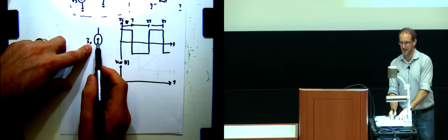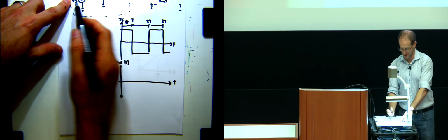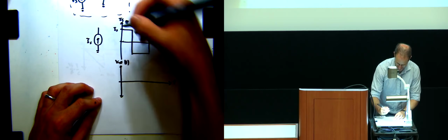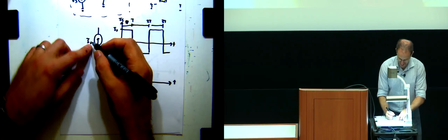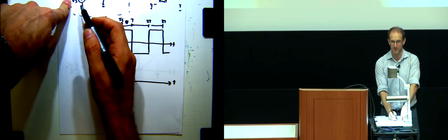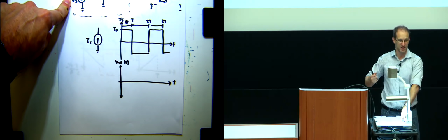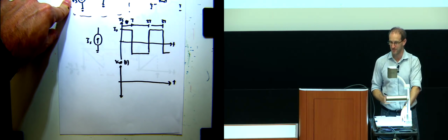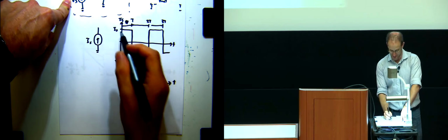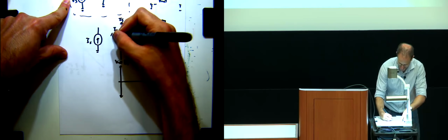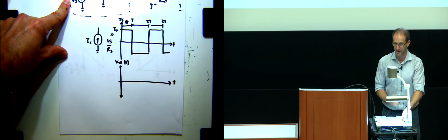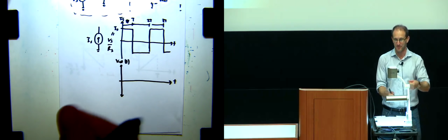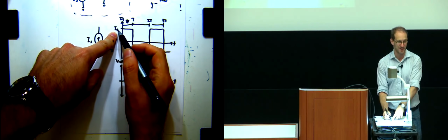And by the way, maybe I should have been even more clear. To get this kind of IS, notice the VS would now also have this same waveform. So if this is what IS is supposed to be, then the way you'd actually implement it, and this is what you will really do in the lab, you'll take what's called the function generator. You'll produce a voltage that has this same shape of waveform, but its value will be picked such that you get the IS you want. As a reminder, IS is just equal to VS over RS. So you'll pick some RS, and then you'll set the amplitude of that VS waveform to get the IS waveform that you actually wanted.